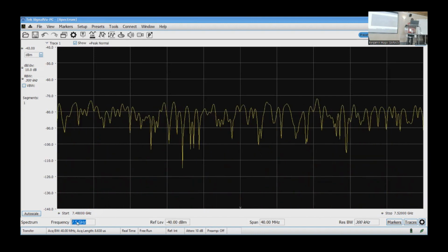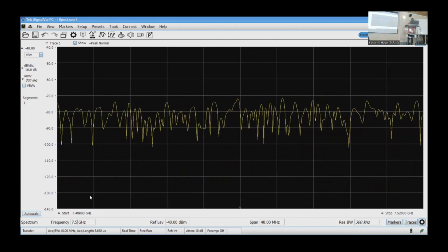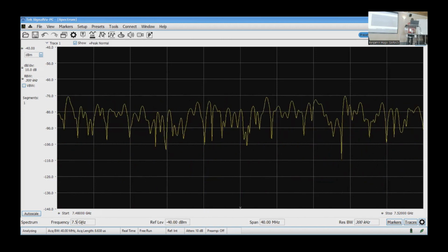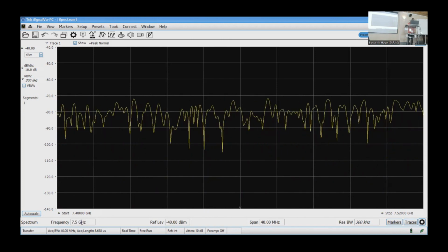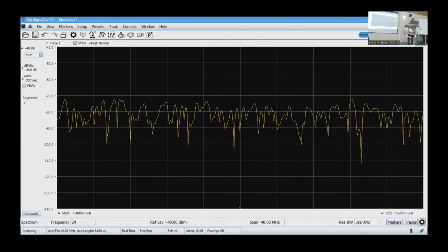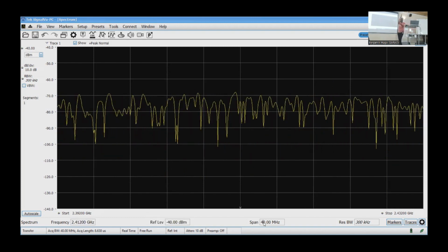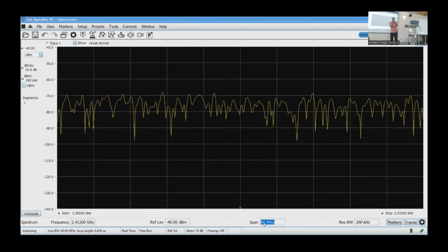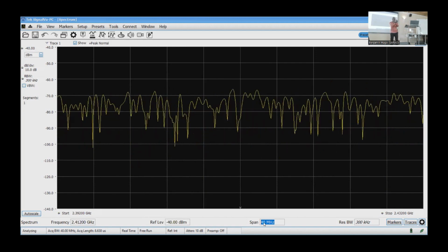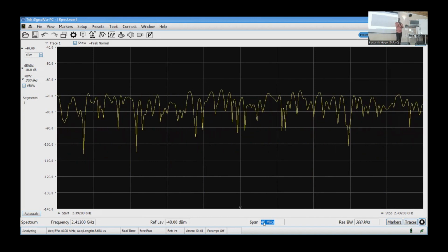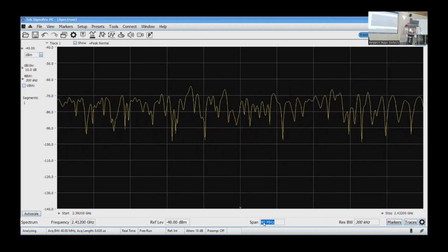This frequency, what did you say? I think you did put the gigahertz. Oh, okay. Say 2412 megahertz. Okay. Now span. So you've chosen your center frequency, but how do you want to span? It's the spectrum around the center frequency that the spectrum analyzer can see. So that's also important. You see, we can put the span.